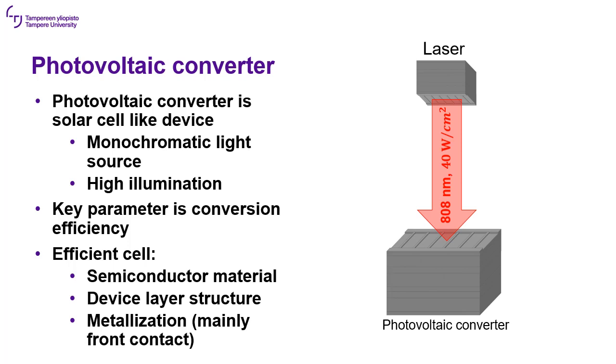They are used in power over fiber applications where energy is transferred via optical fiber and laser light instead of copper wiring. This application has a few advantages over copper wiring, such as galvanic and electromagnetic isolation, and also it is a spark-free energy transfer for flammable environments.